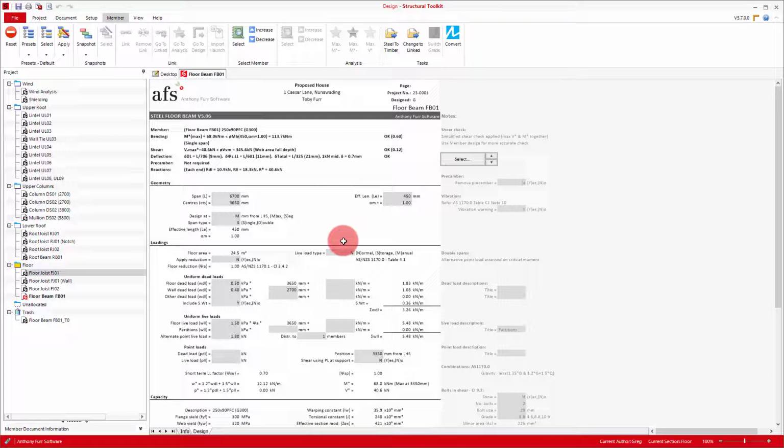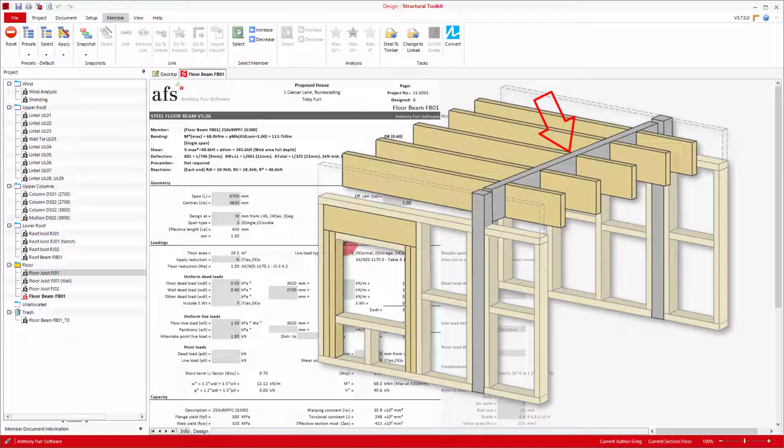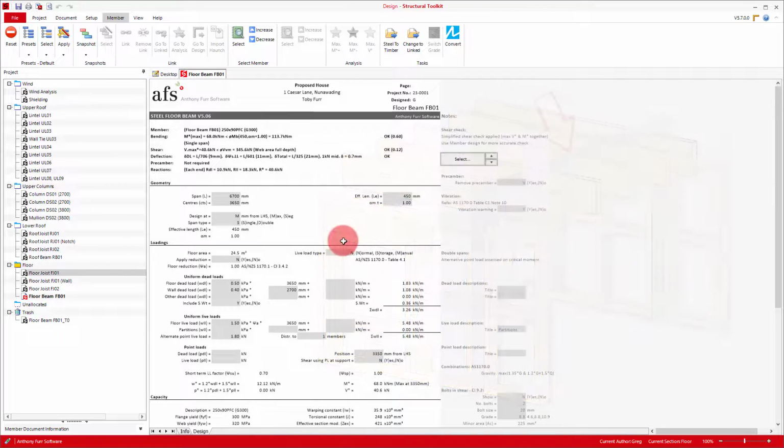However, something to keep in mind is the amount of deflection in millimeters. Floor joists are going to be fixed onto this beam, which already deflect a certain amount. If the beam it is fixed onto also deflects, then the end support of the joist at this point of deflection will also move downwards, effectively increasing the overall deflection of this joist. The concept here is effectively cumulative deflection.